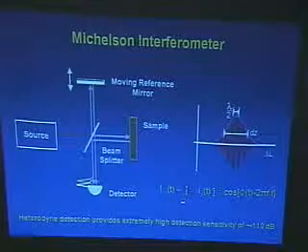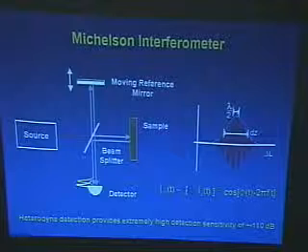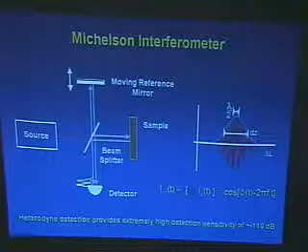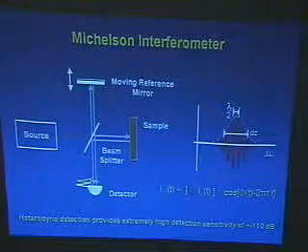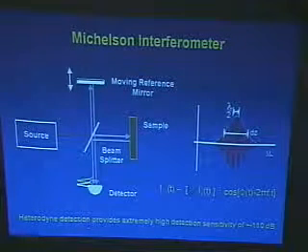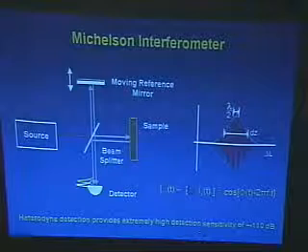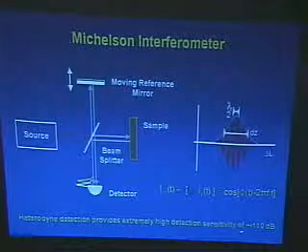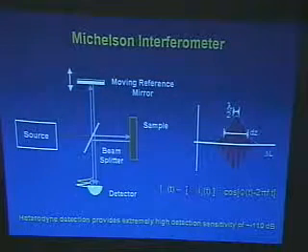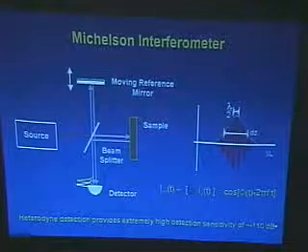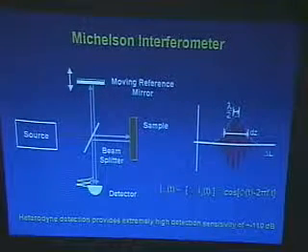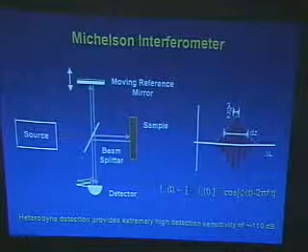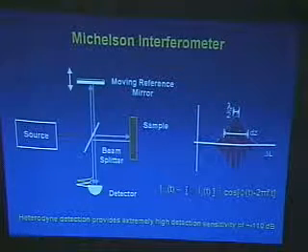This is like an amplifier, an optical amplification, and this amplification in general is huge. It's much more than you can generally do using electronic components. Using this so-called heterodyne detection technique, we can achieve detection sensitivity down to minus 100 dB. Actually, this slide just lists minus 10, but in the lab we can easily reach minus 115 or minus 120 dB.